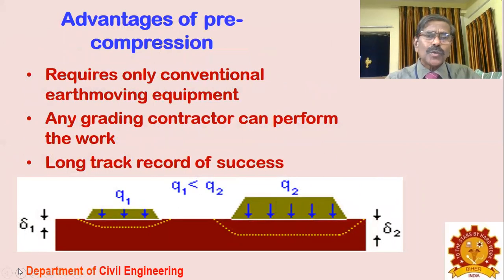The advantage is it requires only conventional earth moving equipment. You just dump soil. Any general contractor can perform the work. It doesn't require any skilled work. It has a long track record of success. So most of the structures have been built on this type of soil treatment. They are all successfully performing their duties without any failure. So a long track record of success has been achieved because of preloading.